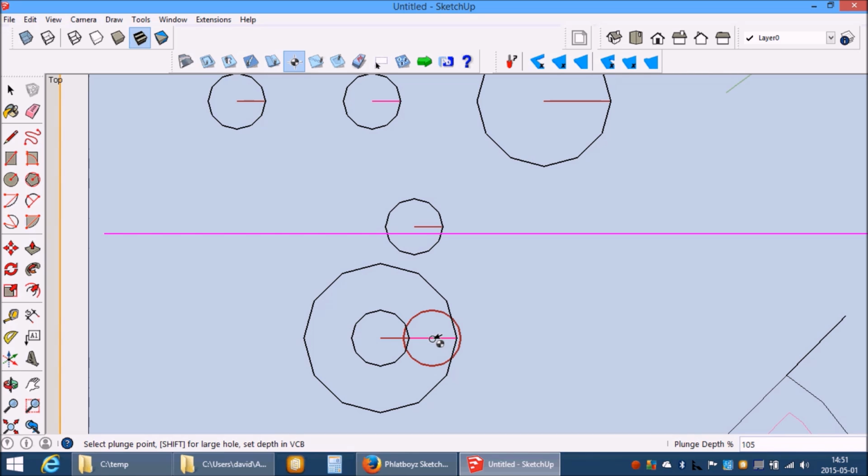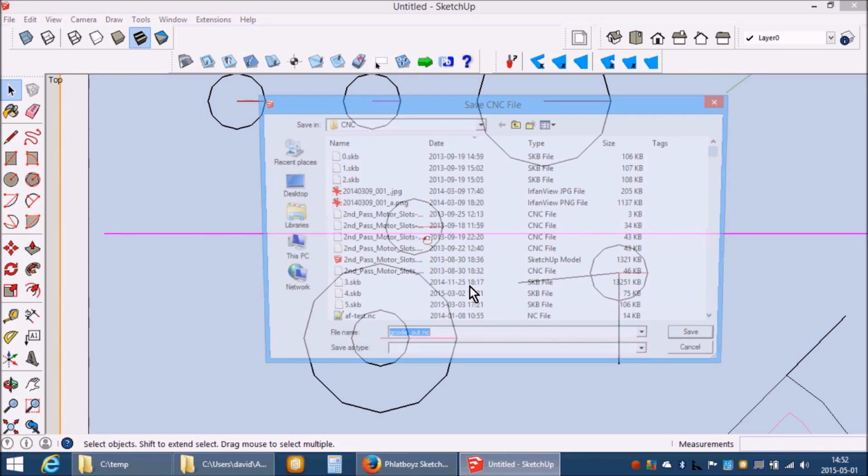As you can see, I've done a partial depth large hole, and the color of the cut line has changed. Holes are a little bit special in that they do not like to have intersecting lines through the hole. That particular line will create some very odd things in the Gcode output. In fact, possibly drilling 2 holes. So don't do that. You can, however, do something like this and use that as the marker for a center for a hole. That will work just fine. It's when it intersects with this horizontal colored portion of the hole drawing that there is a problem.